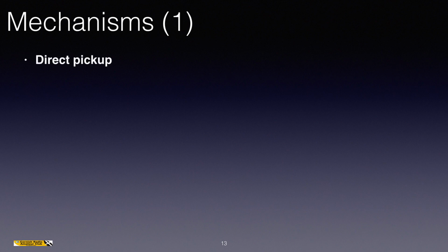We talked about direct pickup. Direct pickup is where the antenna radiates the signal and it goes straight into the components. So if you had a hi-fi setup and you were sure that it wasn't mains-borne interference, if you disconnect the antenna into the tuner and disconnect the phono leads, for example, and you still have problems, then that would be direct pickup.